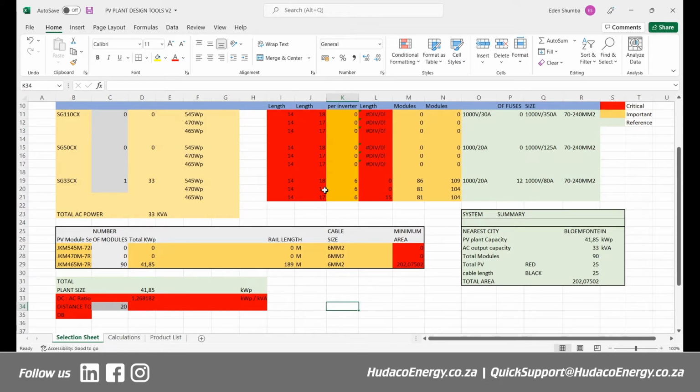you shouldn't be too close to the borders, right? In terms of your voltage. So for example, if you have a string that has 15 panels, and you only leave a margin of say 20 volts to the maximum recommended for that inverter. Like say you add up panels that give you up to, say, maybe 970 volts.